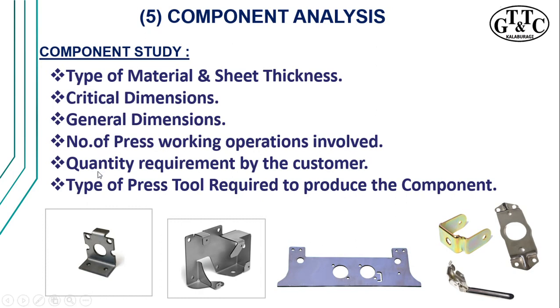And then the next one is the quantity requirement by the customer. So it is very important. For a smaller quantity, it is a crime to design a very complicated tool. So generally, most of the time the customer may require a small quantity. Then it is advisable to design a single stage tool. It can be a separate tool for blanking or piercing and then bending. So that is most advisable. So quantity matters. In case of mass quantity, it is advised to go for a progressive type of